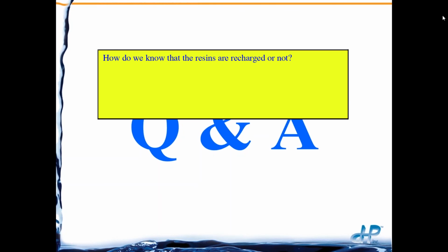So it's the work done, right? The work to remove the ions is based on what's coming out, which is virtually zero, and the amount of ions entering the stack. And you look at flow rates, and you look at Faraday's constant. It's complicated, and I can certainly share the equation with you, but it would tell you the current efficiency you're using. And the current efficiency tells you how much water splitting is occurring in the stack.